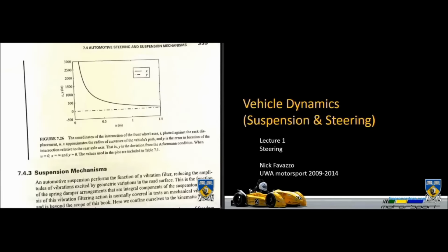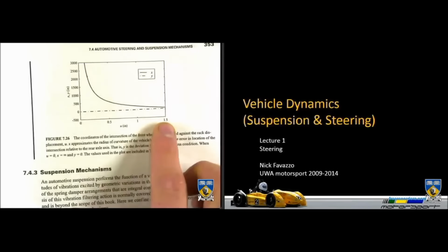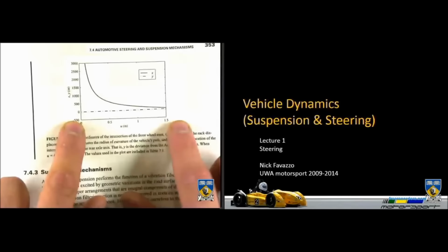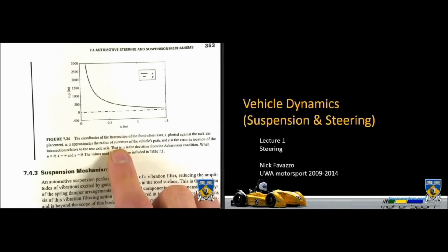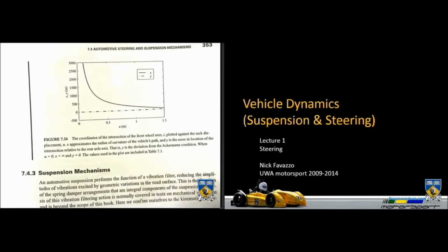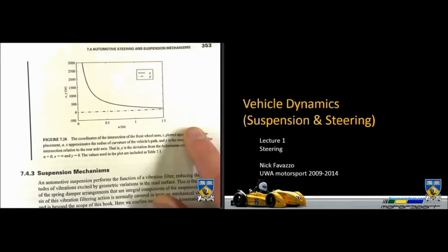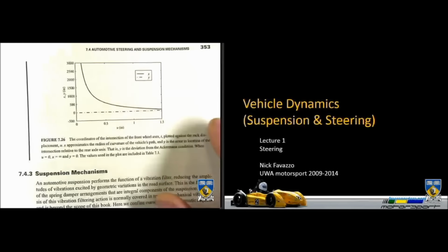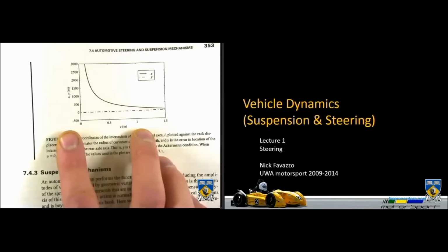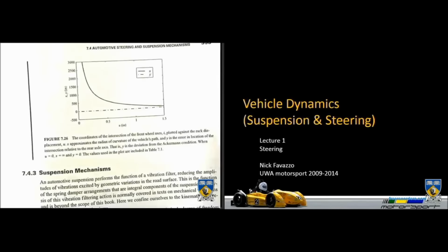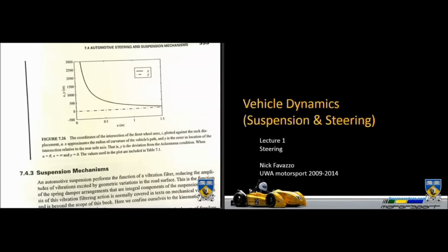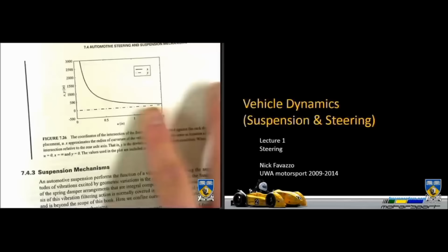Next up, y is the error from perfect Ackermann. So that dotted line going across there, you can see that it's slightly not at zero the whole way across. So for small mu, it's actually quite a good approximation for the Ackermann condition, and as displacement increases, it tends to not closely follow Ackermann. But for all intents and purposes, you can design around a maximum range of 0 to 1 inches and have the associated ratios on the steering side of things inside your wheel so that you're not actually going outside that close approximation.